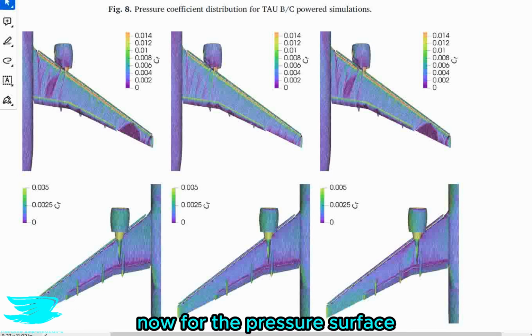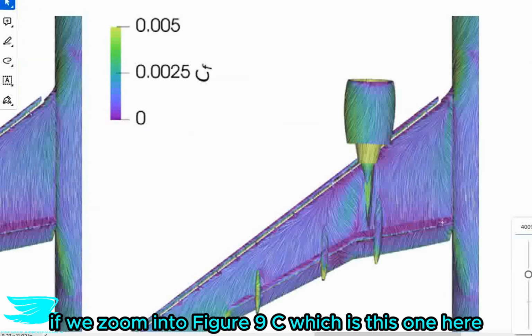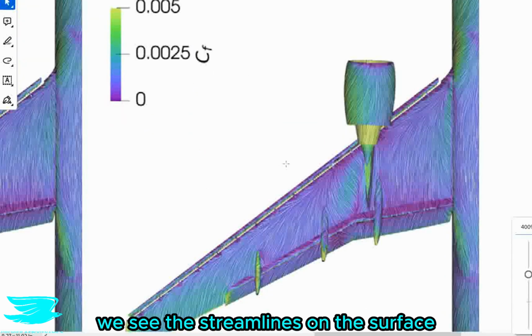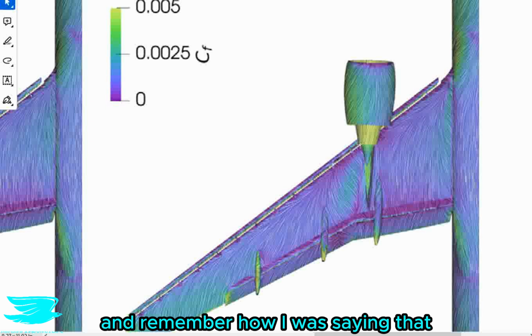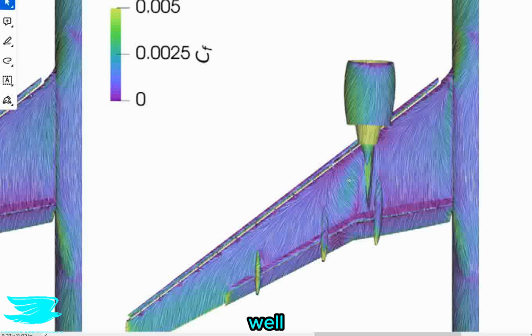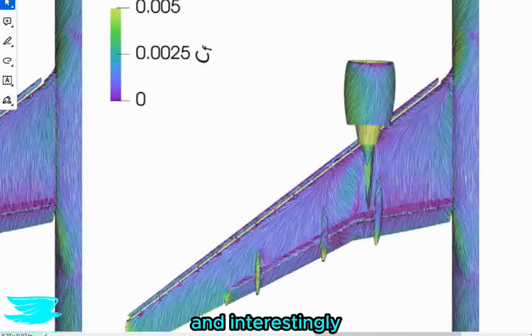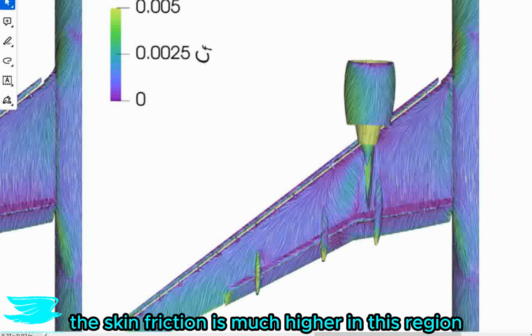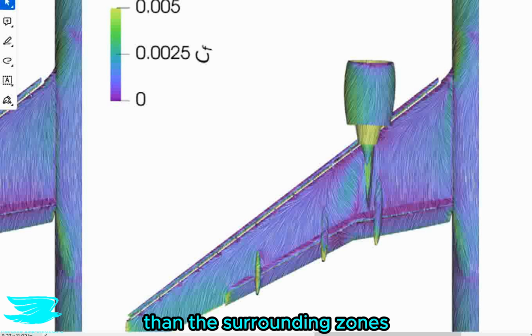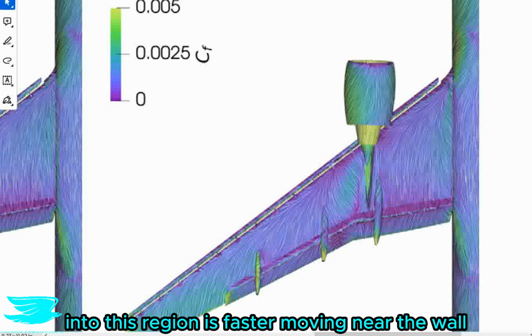Now for the pressure surface, if we zoom into figure 9C, which is this one here, we see the streamlines on the surface. And remember how I was saying that in the downstream region of the engine, a lot of the flow is being drawn into it. Well, we see the exact same thing happening here where these streamlines really get sucked in here. And interestingly, the skin friction is much higher in this region than the surrounding zones. That tells us that the flow migrating into this region is faster moving near the wall.